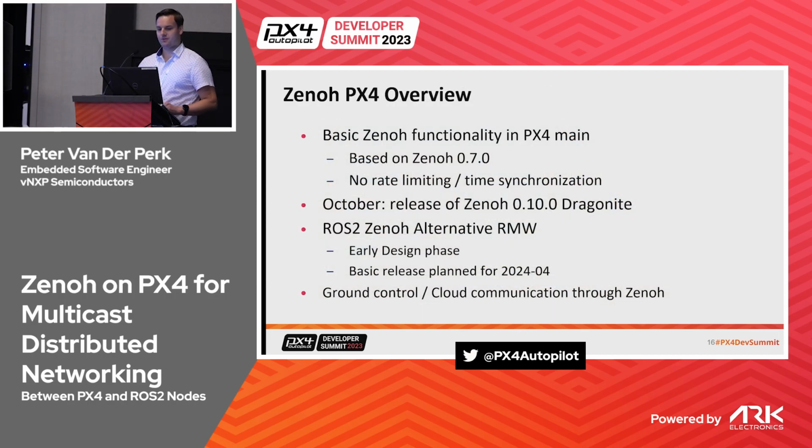So, kind of an overview. As of this week, Zenoh is in PX4 main. It's based on a bit older version of Zenoh, because they're developing quickly, so you kind of have to bear with me. I still have to write the documentation to make sure that you install the right version, because you have some incompatibilities. Fortunately, right now there's no rate limiting. So if you're going to use it for applications, you have to make sure that you're not going to overload the FMU. And as of October, there's now the newest release, so hopefully in coming months, I can also implement that one.